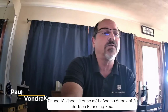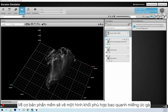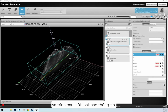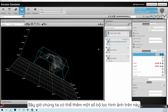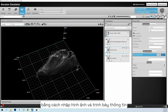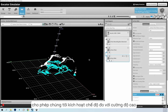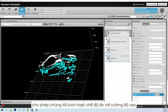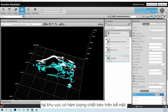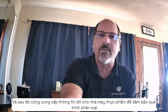We're using a standard tool called the surface bounding box that basically draws a best fit box around the chicken breast and presents a whole host of information. We can now add some filtering to basically binarize the image and present it into an additional tool called Surface Blob, which then allows us to measure in intensity mode the area presented of the fat content on the surface, and then provide that information as well for a grading process.